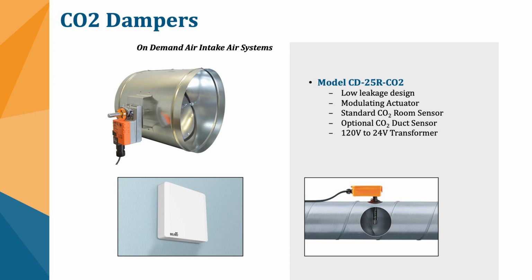One question I get a lot is that most people are used to, say, fire smoke dampers with smoke detectors installed, or things where everything's kind of wired together. And that's a little counterintuitive when you're dealing with CO2 sensors. Typically, the CO2 sensors are going to be measuring in a room, so you're actually in the occupancy, which is going to be probably a bit detached from where you want to install the damper to open and close to allow that outside air to come in as your fans kick on and turn off for that system. So you're typically not going to want these installed with the damper.